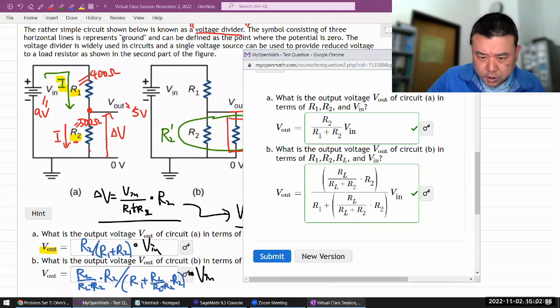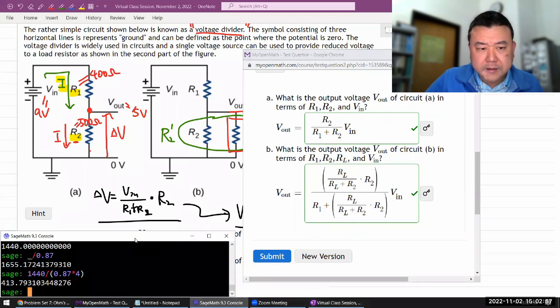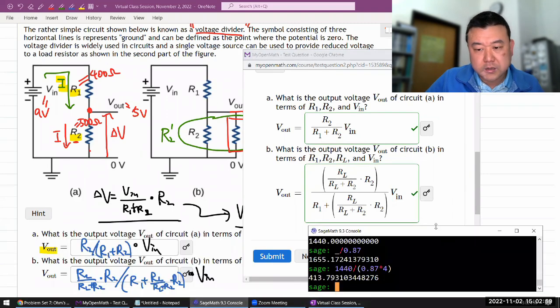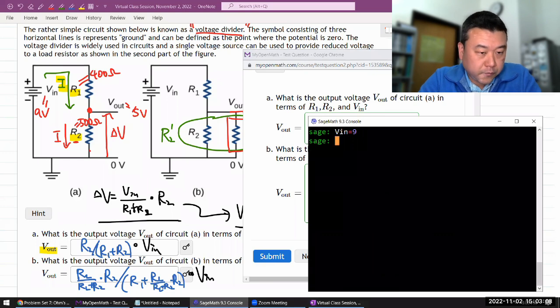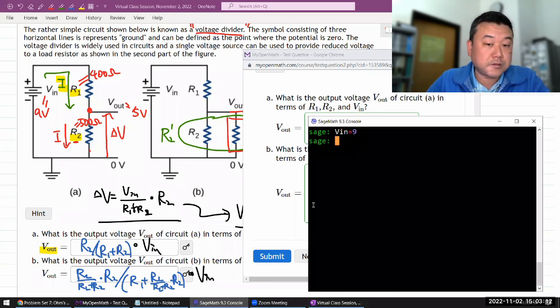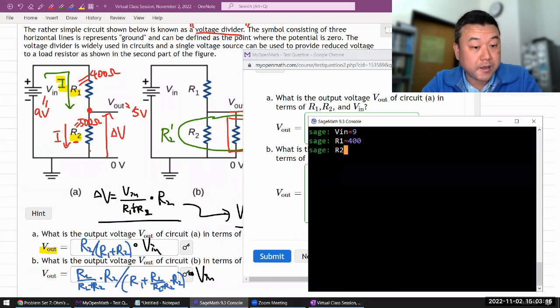And this is the thing I want to caution you about. So let's take the example that I used. Imagine I had a 9-volt power supply that I wanted to get down to 5 volts for some usage. So my input voltage is 9 volts, and I chose these two resistor values based on what's in my drawer, and let's say they seemed reasonable at the time when I picked them.